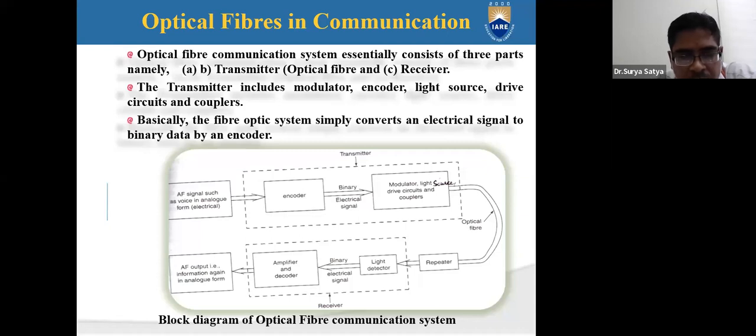The only difference between single mode and multimode step-index fibers is that the core has a larger diameter. The core diameter is 50 to 100 micrometers, which is very large, and the external diameter of the cladding is about 125 to 300 micrometers.